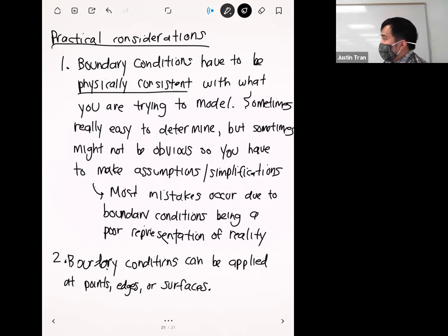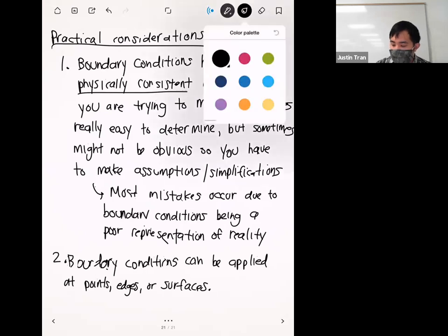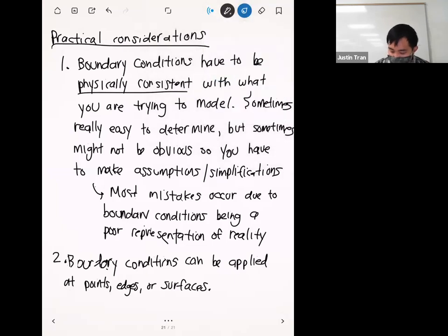And so what you end up choosing, of course, depends on the nature of the physical situation that you're trying to model, okay? But generally, you want to apply boundary conditions on the largest entity possible, okay? And so for 3D simulations, that means surfaces, right? And so generally, if you can, and sometimes it doesn't make sense, and I get it, but for 3D simulations, if you can form your boundary conditions in a way such that you're applying it on a surface or a face, that's usually going to lead to the highest quality and the best solution. Okay.